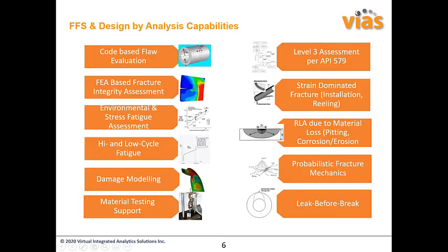And then we have a very hardcore specialization in the fitness for service level 3 assessment for different types of structures, which include pipelines, basically the drums and the tanks and several other infrastructures, so we can model the fracture geometry, and then we can predict the performance of that structure and the growth of the crack based upon the codes.